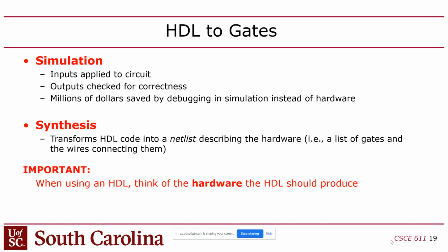So now you might say, well, why would anyone not simulate? Well, okay, there's a problem. So you guys, I notice in this class, students will generally get into a habit that they prefer. They like to write the code and go straight to the FPGA, or they might just go to simulation and they don't want to use the FPGA at all. Everyone gets into kind of a habit, but I encourage you to learn both design flows, the simulation and the synthesis design flow, right? The pathway. They have different paths and different compilers that lead you to different things. In one case, you're basically testing, and the other one is you're actually building it.